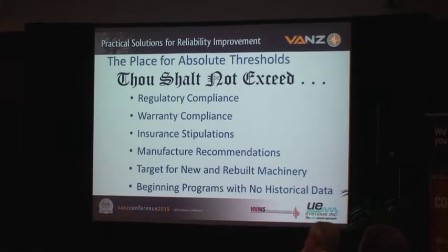Interestingly enough, when you look at the regulatory 0.325 inches per second being the threshold of concern for machinery in a nuclear power plant in the States, that's also an insurability requirement. If you've got a machine that exceeds 0.325 inches per second and you don't address it, not only did the Nuclear Regulatory Commission want to have a little chat with us and were happy to impose a fine if we didn't respond appropriately in their opinion, our insurance carrier would up our rates because of the perceived increase in risk.